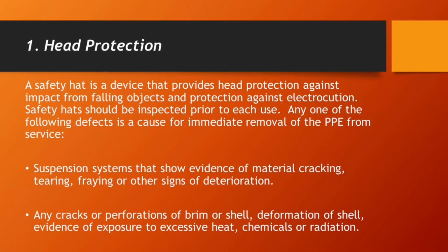For number 1, head protection. A safety hat is a device that provides head protection against impact from falling objects and protection against electrocution. Safety hats should be inspected prior to use. Any of the following defects is a cause for immediate removal of the PPE from service.